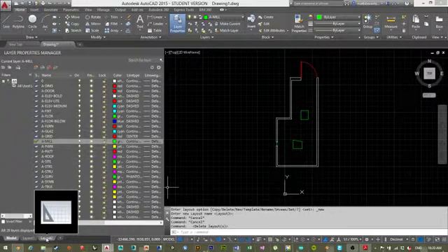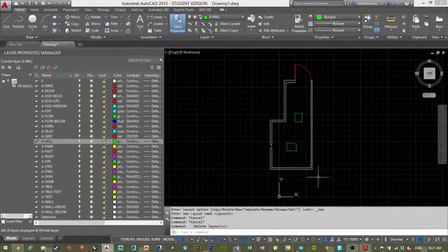So on a project that I've been working on, I might have an 8.5 by 11 page, A1. If I have multiple levels on a building, I'll do them all in the same AutoCAD file, but I'll have level 1 A1, level 2 A1, level 3 A1, and you can set up all those pages one time, and then do multiple versions, or keep on editing your actual drawing, and those pages will automatically update.